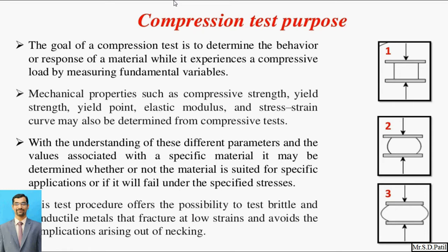The mechanical properties like compressive strength, yield point, elastic modulus and stress-strain curve may also be determined from the compressive test. So whatever properties we can determine through the tensile test, those properties again we can determine by conducting the compressive test.